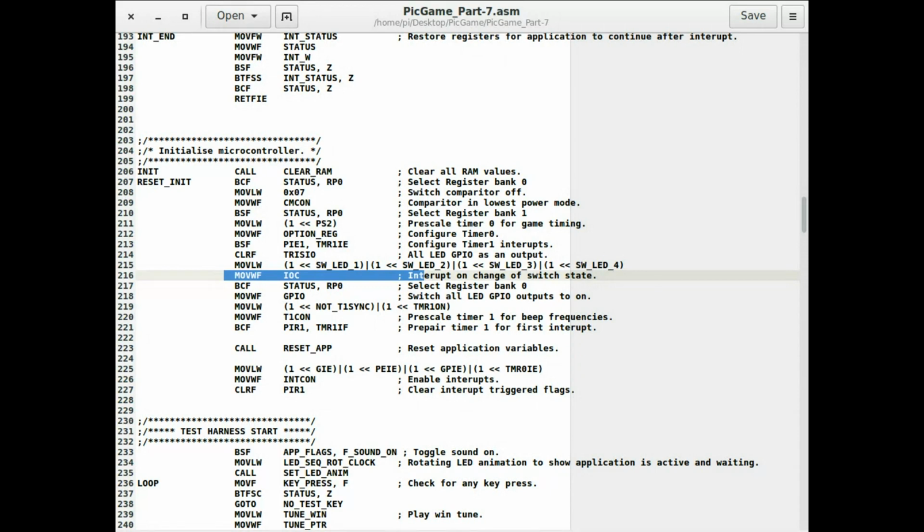And then there's the GPIO interrupt enable we've added as well, interrupt on event happening to input, and also interrupt on timer 0. We've added that there as well. And then up here on the option register, just one other thing, we just set a prescale for timer 0.